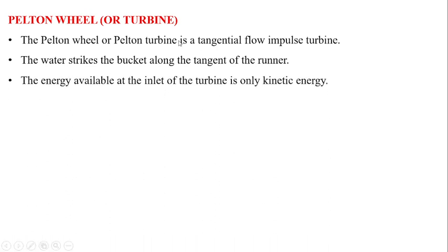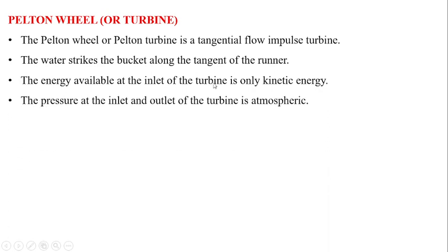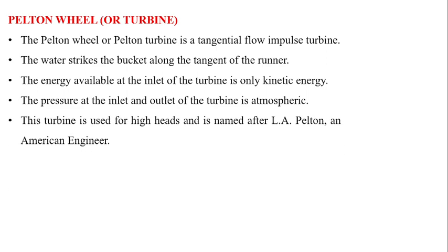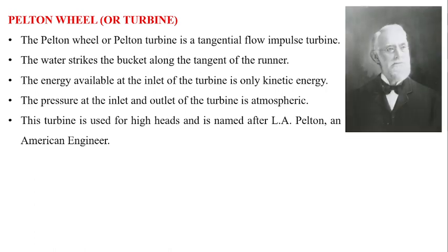The energy available at the inlet of the turbine is kinetic energy. The pressure at the inlet and outlet of the turbine is atmospheric pressure. The turbine is used for high heads and is named after L.A. Pelton, an American engineer who invented this Pelton wheel.